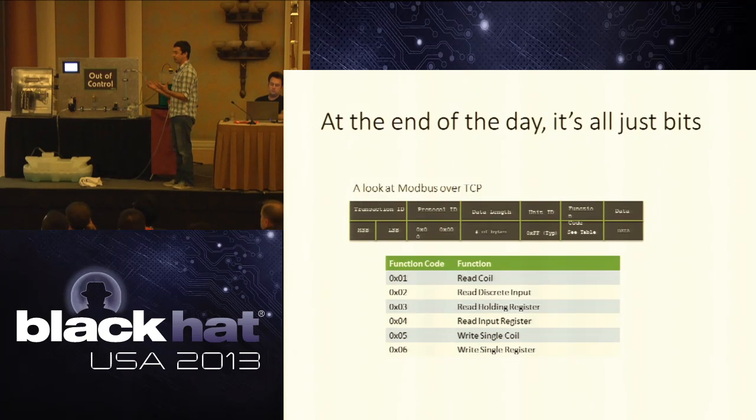So we want to construct a Modbus datagram. So how do we do that? Well, the Modbus datagram is actually extremely easy. It's extremely simple. First, the very first bytes are a transaction ID, and the reason why that's kind of cool is because that's actually a legacy of an older serial protocol. You don't need this transaction ID anymore, right? Because that's handled by higher layer protocols, but they still have it in there to maintain compatibility with the older devices. A protocol ID is always 0. It's always 2 bytes of zeros, no matter what.